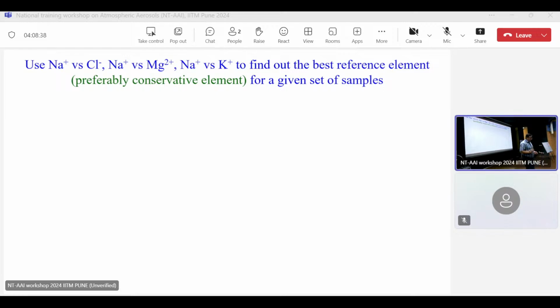This sodium chloride plus sulfuric acid: since sea salts are coming and you have a power plant producing sulfuric acid, they are reacting. It will form sodium sulfate. It will remove chloride, but it will not remove sodium. That means sodium is staying in the system. So we call it conversion. So sodium, calcium, magnesium, potassium, all are converted.